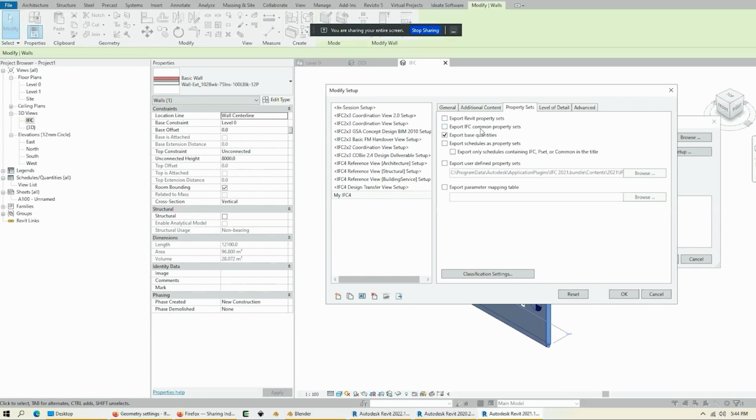If a structural model has fire rating data, do I really trust the structural engineer to have that correct fire rating data? Probably not. And do I trust the architect's model to have the is external or load-bearing data to be correct in every single wall? Also probably not. So what I'd advise is to, again, just disable that. So you notice we had that enabled before.